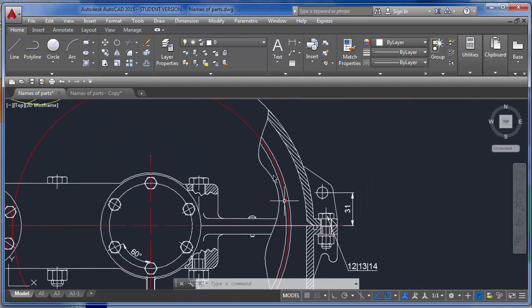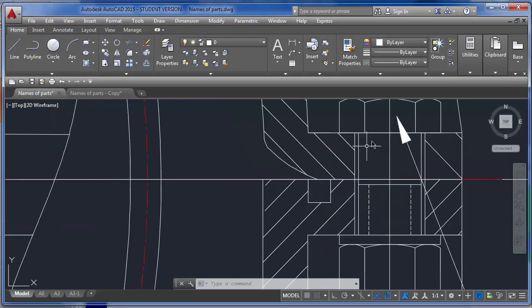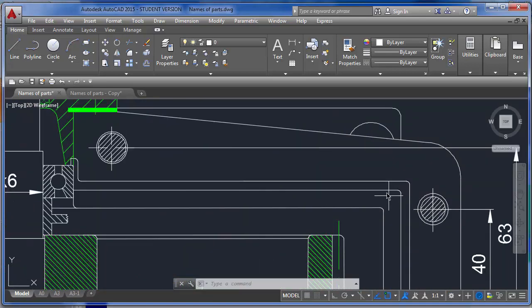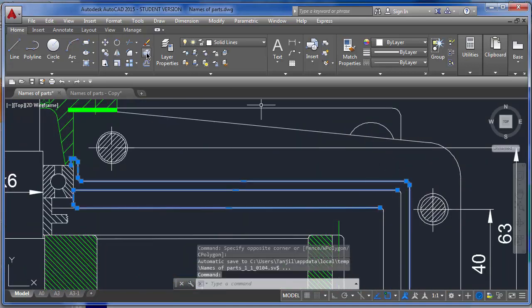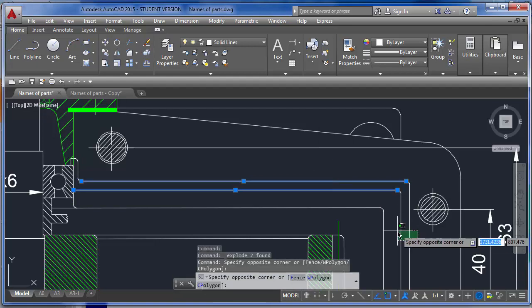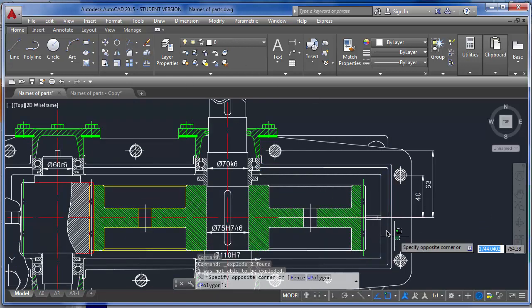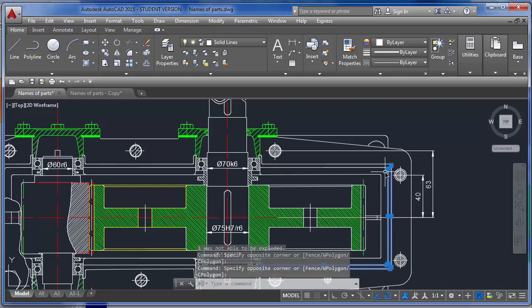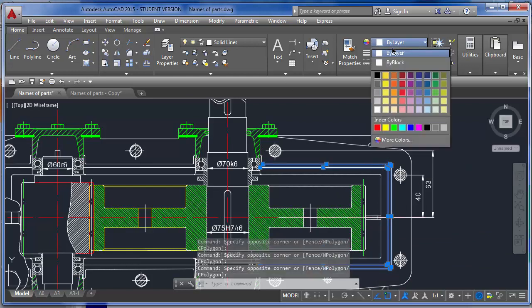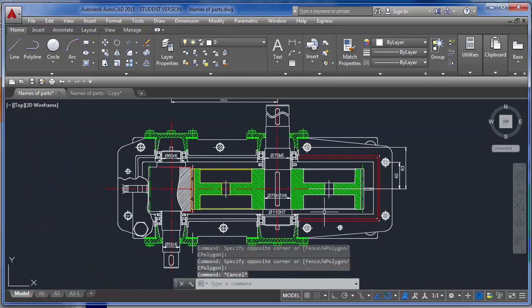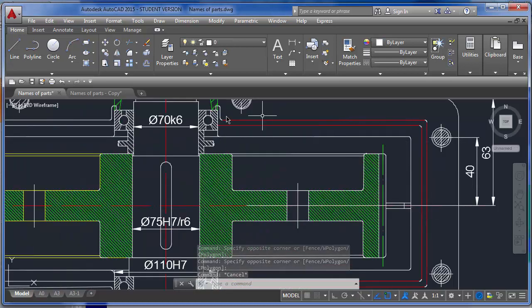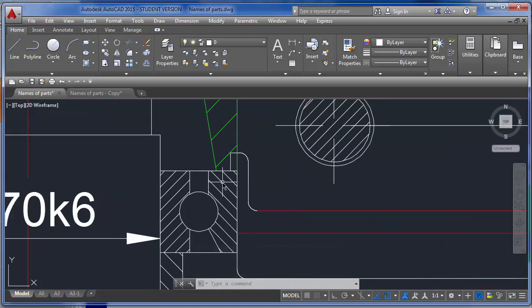So engine oil hits here, goes to this groove, and from the top view, these two lines are actually grooves. So you see, oil is collected here and goes all the way down to this bearing. It's not going directly through here because this is the outer cover, the outer race of the bearing. There's no hole here. We put it from the side.